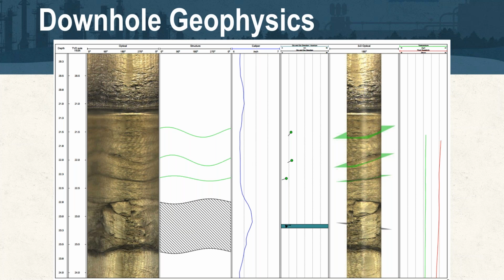But even those best efforts can be thwarted in the field, whether it's over time or just degradation. Recently we did a site here in Pennsylvania where the borehole had only been installed about 6-8 weeks before we went out there. Because of some high angle interconnected fractures, there was significant natural spalling on the inside of that borehole, so we definitely had to take that into account. It didn't preclude us from analyzing that zone, but aging in some of these softer, less competent materials could be a consideration, once you move out of the transition zone, in how well that works.